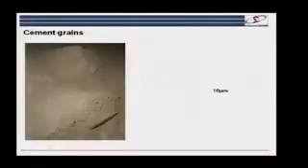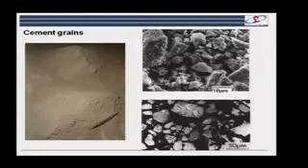You've got a big amount of thermal shock when you cool it, which causes these cracks, and then the fracture is going to go through the grains, and the different grains are generally going to have all the different phases in them. So when we come back to talk about these different phases, C3S, C2S, aluminate, etc., they're not existing in separate grains. They're all together in the same grain.